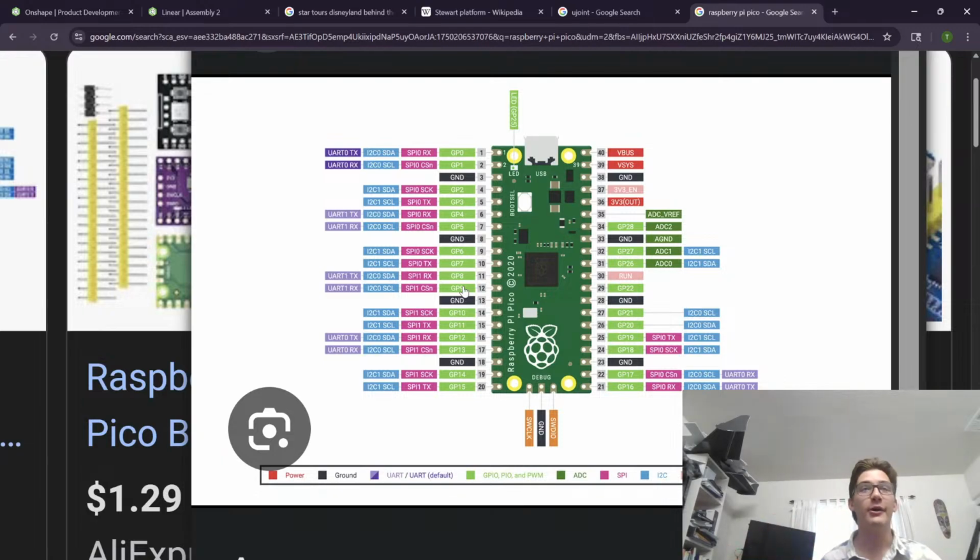If I somehow end up doing it wired, or if I end up having a full scene that has multiple animatronics, I can communicate between all the animatronics through CAN bus and devote one as the master. So the Wi-Fi network will only need to tell the master, start the show scene, and it communicates with all the other animatronics or special effects through that CAN bus, and the whole thing plays in synchronicity, which could be pretty cool. So I'll leave at least one of the SPIs open,